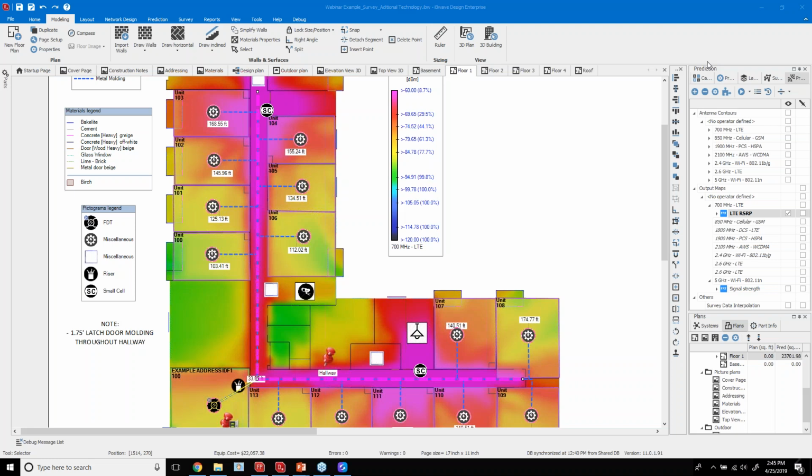Yeah, so that goes back to the first question. Again, the technology being developed to support MDU applications from a carrier perspective is geared more towards single mode. So that would be my default answer. But certainly if you as an operator are more experienced with a local area style network, indoor networks using multi-mode fiber, and you're able to provide the service packages over an Ethernet style deployment, and it's just a data package, then certainly it would be worth evaluating the multi-mode fiber type as your cabling solution.